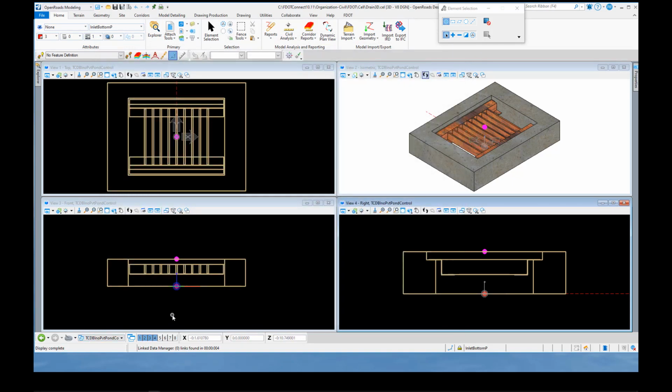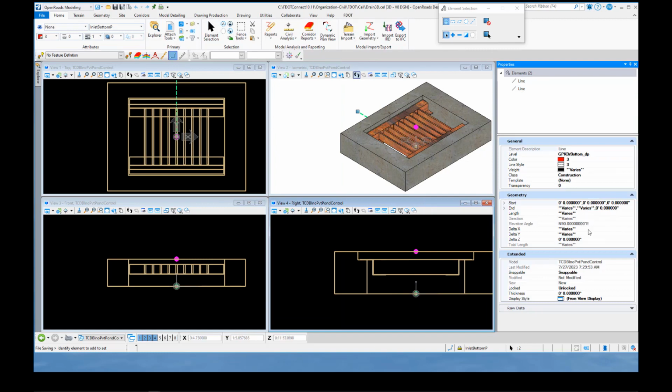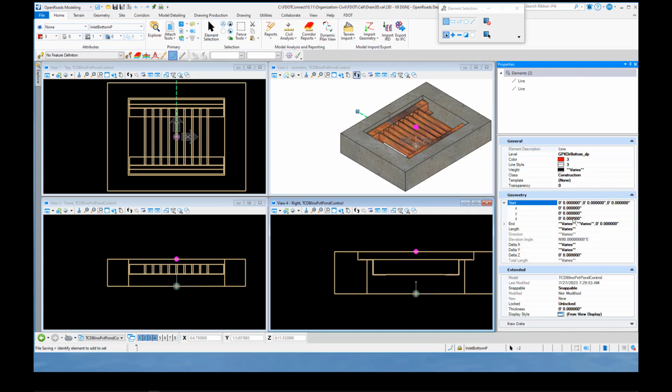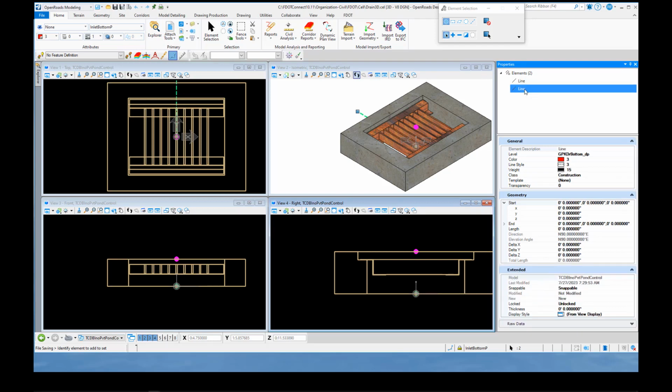All right, now one thing that I have to stress here more than anything else, this is a 3D top cell. So this line and this point have to be at 0, 0 with their starting point. So you have to see all zeros here when you're looking at the line, which is for alignment, or the point, which is for location.